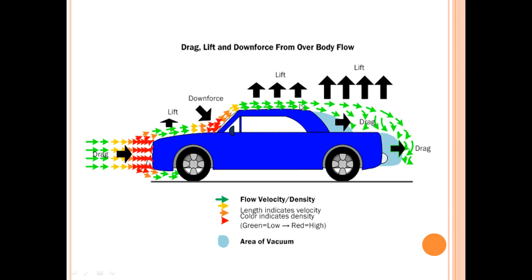At the hood section, at the roof section of the vehicle body, the velocity is increased and the pressure is decreased. When the pressure is decreased, a lift force will be acting, sort of trying to suck this hood up from the vehicle. Trying to suck this hood or roof from the vehicle.